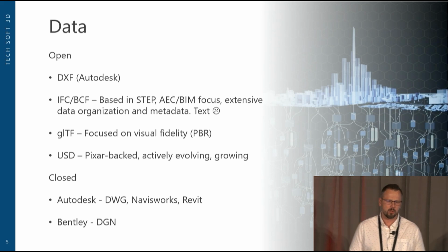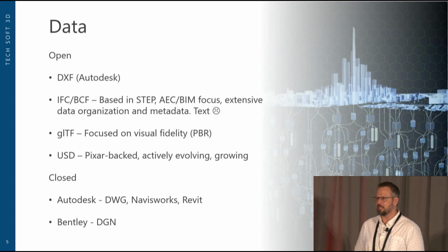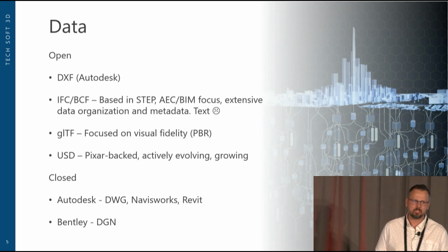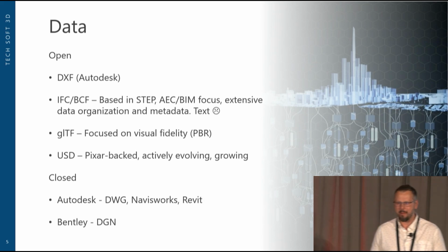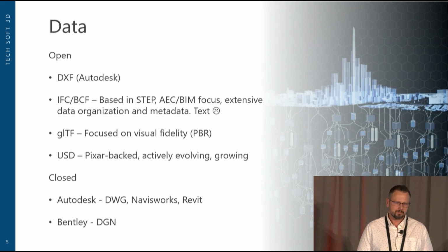So important. There's a number of different formats that data can exist in. Originally, really, it's Autodesk that has dominated the AEC industry with their applications and, of course, their data, and they aren't exactly open about how they share that. However, one format is used for interoperability. It's quite old. It's DXF.